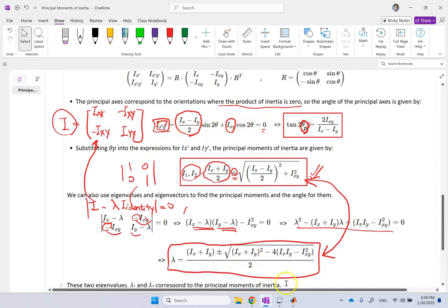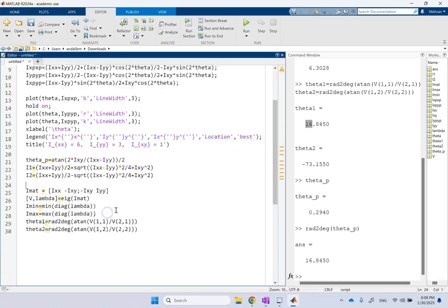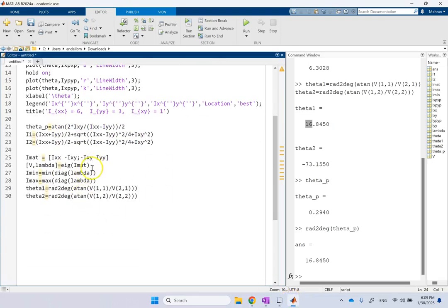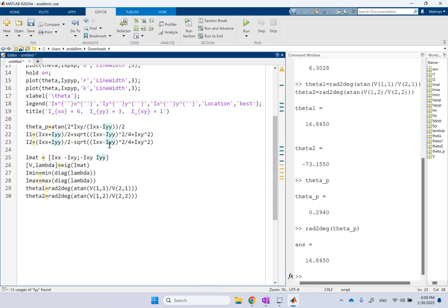The best way to do it is just form the inertia matrix, which is 9 numbers, and then use the eigenvalues and the eigenvectors. And clearly, the eigenvalues are the numbers of the lambda matrix, because remember, your lambda matrix is going to be a diagonal, so it has 3 diagonals, and one of them is min, one of them is max, one of them is in between.